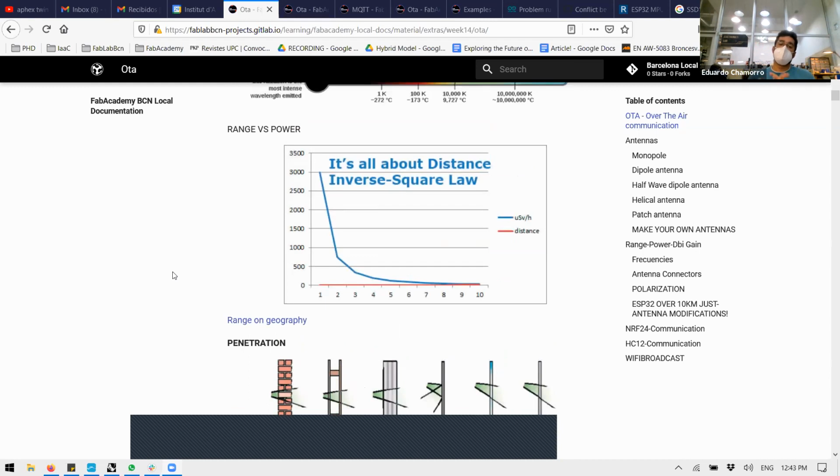What also happens when augmenting the power? For example, I just remember that in Europe the maximum emitting capacity of any Wi-Fi device is 100 milliwatts. So any router will only emit at 100 milliwatts. A bad router will also emit, if it can, at 100 milliwatts. Another thing is the stability of the emission. You can have a device that emits a really constant power, and another one with a DC buck converter that is not stable, which influences the amplification module.